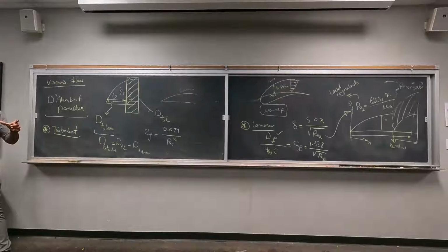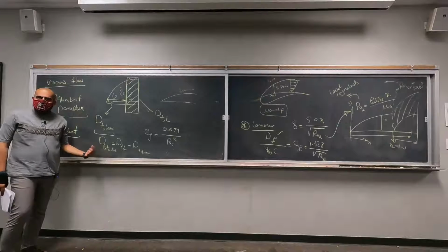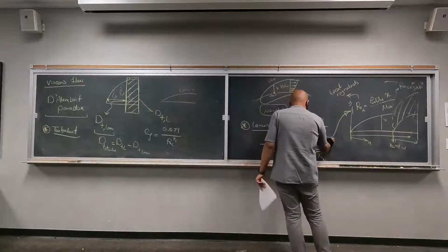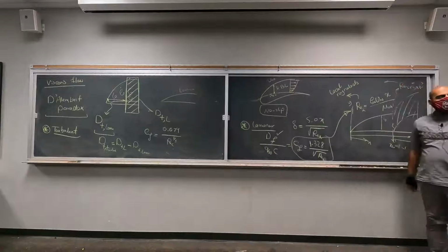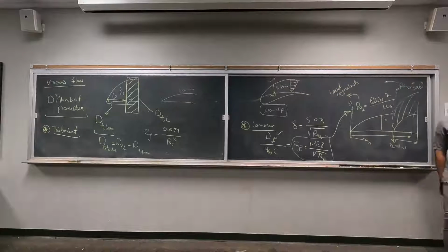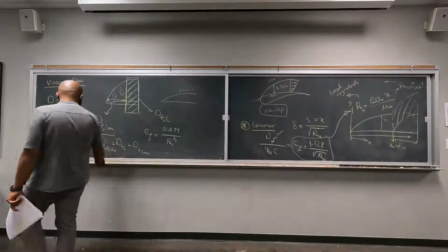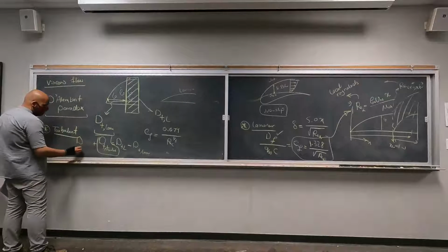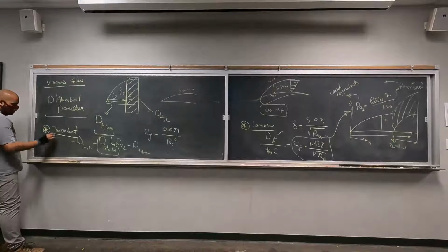You're only going to have the turbulent drag where the flow is turbulent, and then for the laminar region, you just use the C_f, the laminar equation, make the calculations, find the drag force, and add this to your turbulent calculation, and that will give you the total friction drag, D_F.